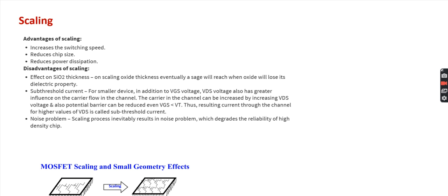Further, you need to reduce the delay or balance the circuits. We can balance them by introducing some buffer circuitry in between. The very important thing is that you should not use cascaded circuits, because if you use cascading, glitching power dissipation will occur. So try to avoid the cascade implementation. It is then possible to minimize your glitching power.